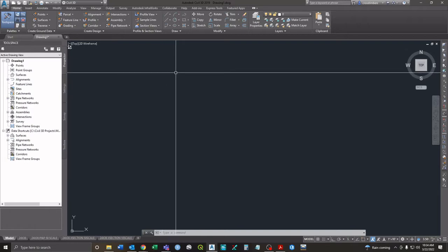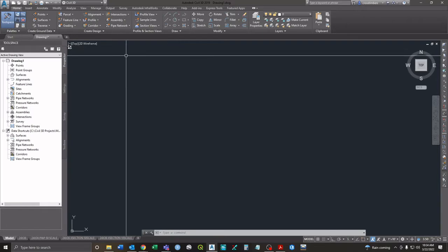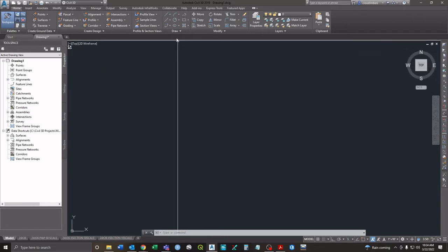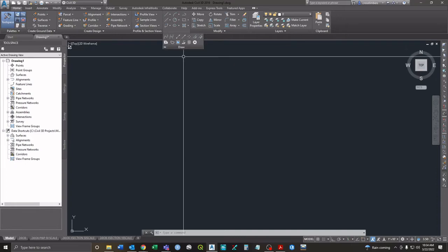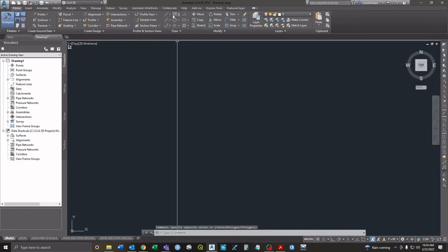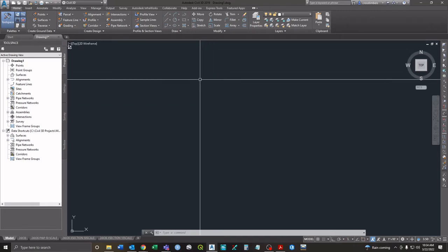Okay. But most of your basic tools that you would pick from a menu are pretty much right here on the Home tab. Under Draw, this is all the basic drawing functions. You've got line, arc, polyline, circles, rectangles, all that stuff. And over here in Modify, you've got Move, Rotate, Trim, Copy, Mirror, all this stuff. Essentially, this is the bulk of everything you'll need to know, and we're going to do the shortcuts. You can always click, but to me it's just easier to do the shortcuts.